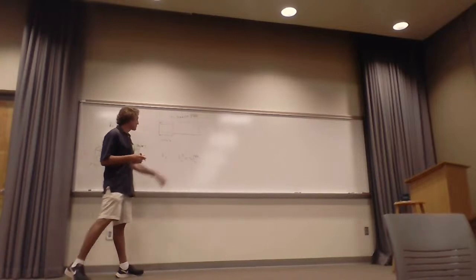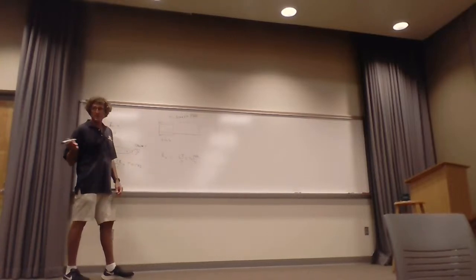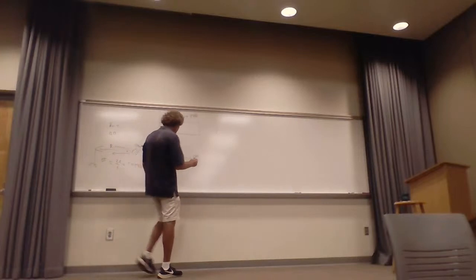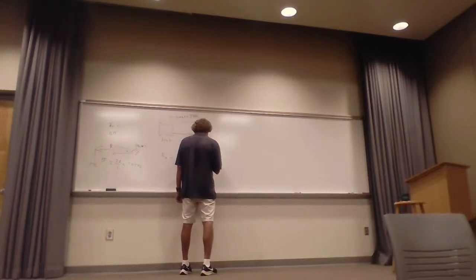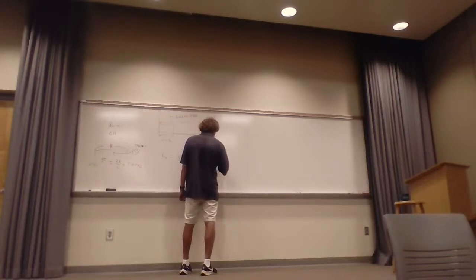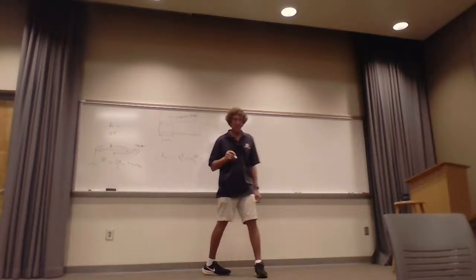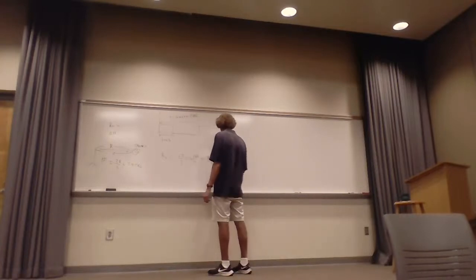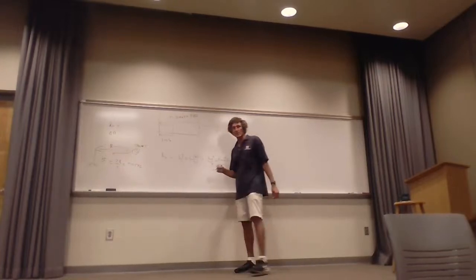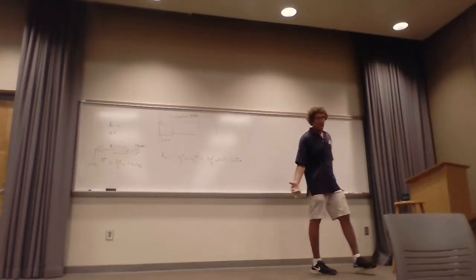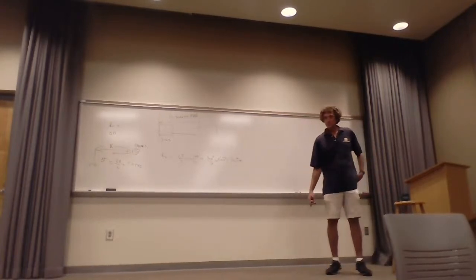So the PRI was 200 microseconds, right? So this would be C, which is 3 times 10 to the 8th, over 2, and the PRI is 200 microseconds, or 2 times 10 to the minus 4th seconds, right? So if you look at that, the 2's cancel, and I have 3 times 10 to the 4th meters, or 30 kilometers. And by the way, 30 kilometers for an airport radar is reasonable.